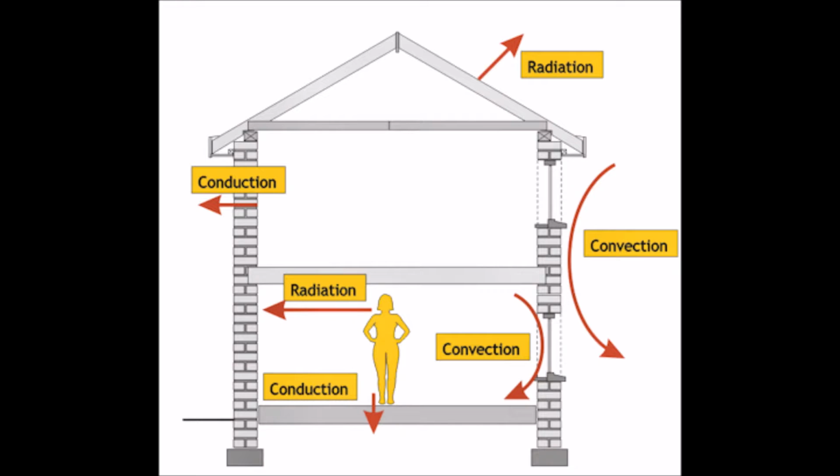Conduction is the diffusion of internal heat within a body as a result of temperature difference across it. This is particularly important in buildings where there may be a temperature difference between the inside and outside of a building, such as in a heated building during winter.